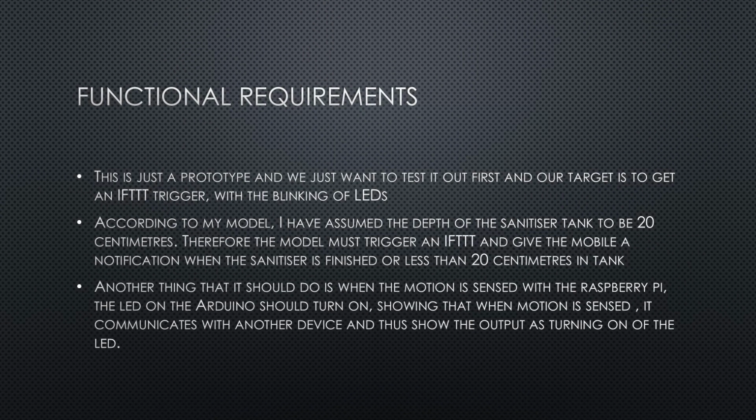Functional requirements for Sanitech. This is just a prototype and we just want to test it out first, and our target is to get an IFTTT trigger with the blinking of LEDs. According to my model, I have assumed the depth of the sanitizer tank to be 20 centimeters. Therefore, the model must trigger an IFTTT and give the mobile a notification when the sanitizer is finished or less than 20 centimeters in the tank.